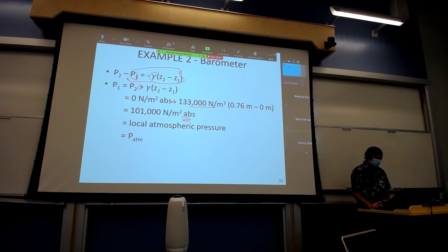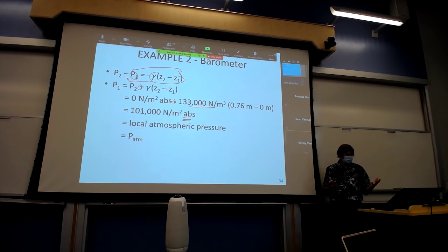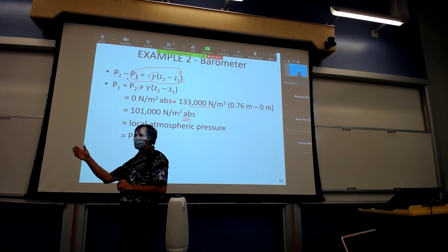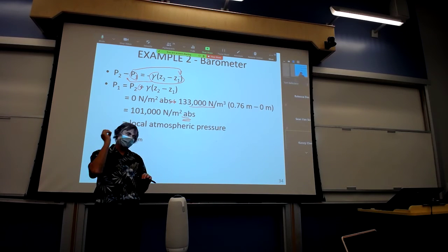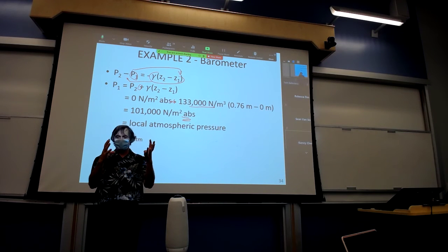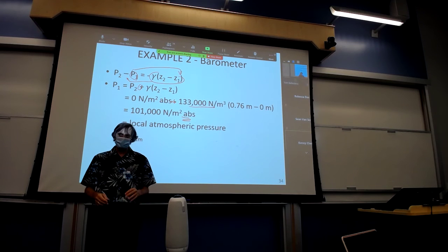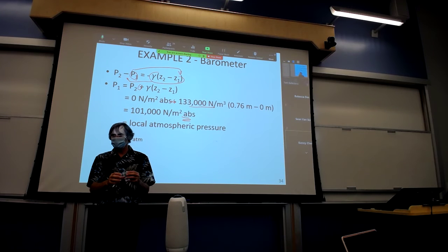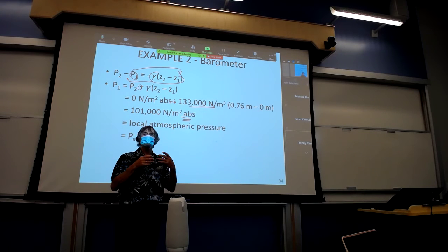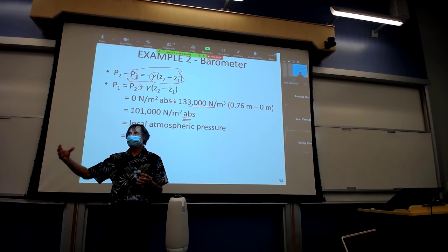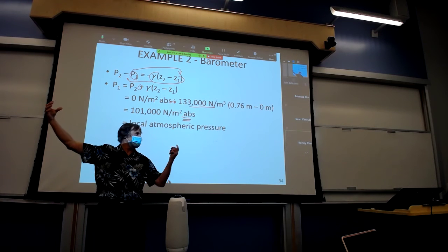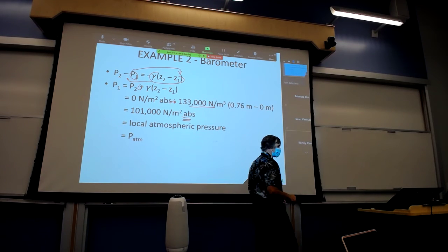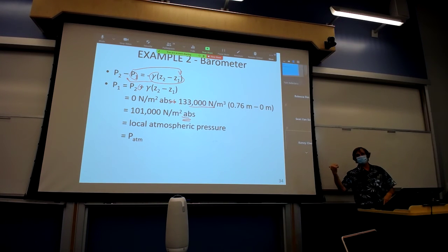And commonly, again, we can have devices, so we'll use pressure transducers, for example, to measure wave height. And when we throw that pressure transducer into the ocean, we'll tie it to a cinder block, throw it in the ocean, and then we'll be measuring the water level over it. Since the pressure transducer is not vented, we have absolute pressure being measured. So we need another transducer above the ground measuring the atmospheric pressure. When we subtract the two, we get the wave height, the water height, which is the class before us, coastal measurements.